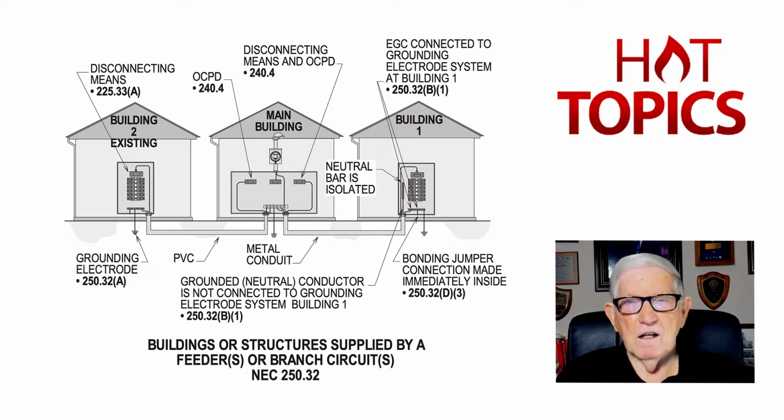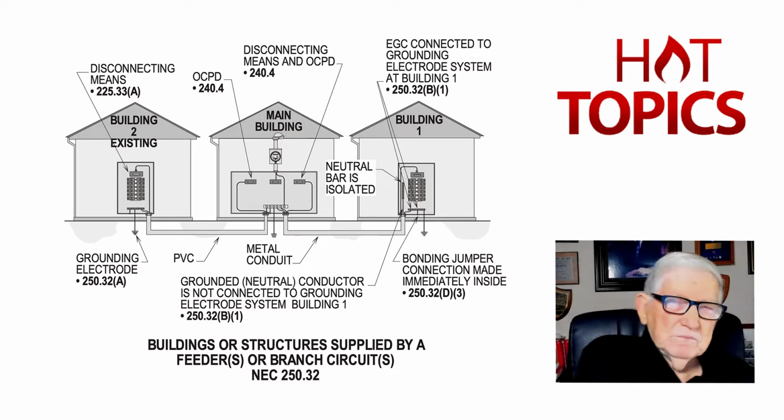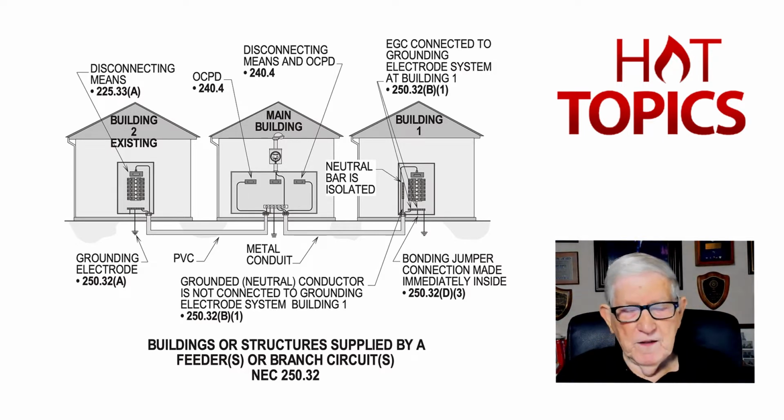But the grounding electrode would be eliminated, just as this individual asked. But notice that permission was given in the 1996 NEC 250-24A exception 2.